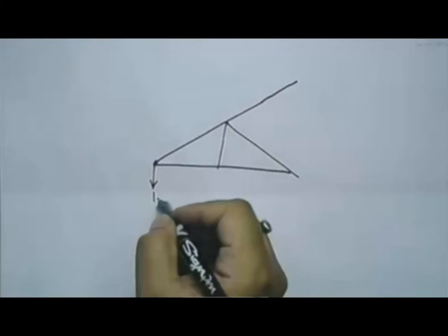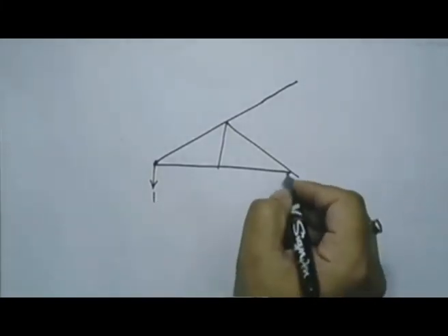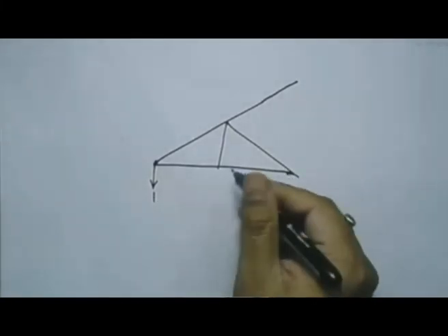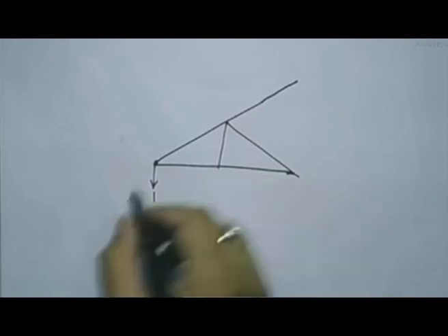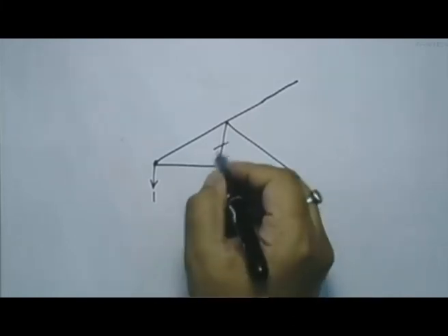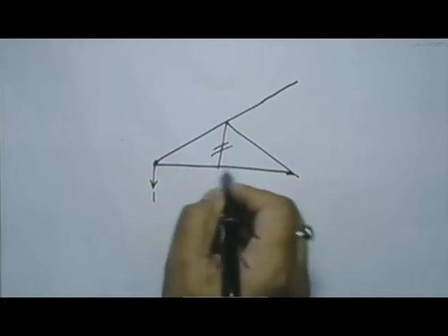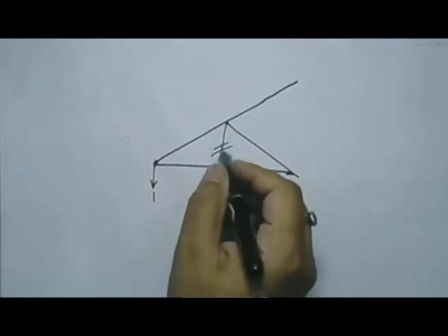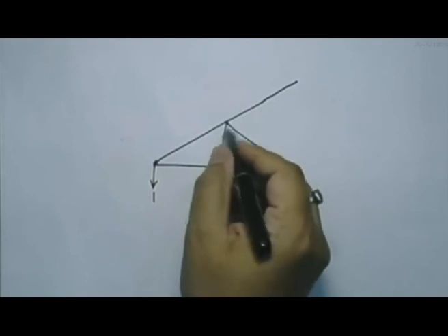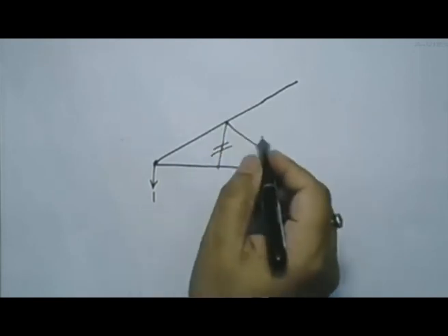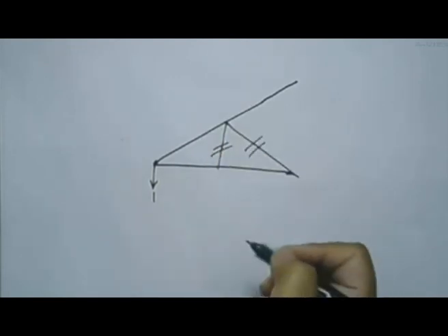If you apply this virtual load, and if you are familiar with the methods of analysis of trusses and joints under special conditions, just by looking at this, you will see that this member is a zero force member, because at this joint, these two members are along a straight line. This is the third member. Similarly, at this joint, this is a zero force member. These two are along a straight line. So these two are zero force members.